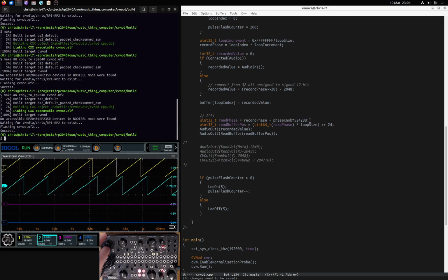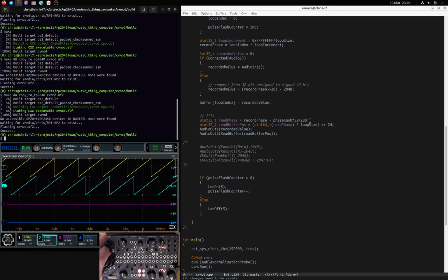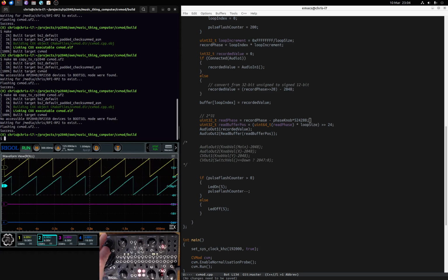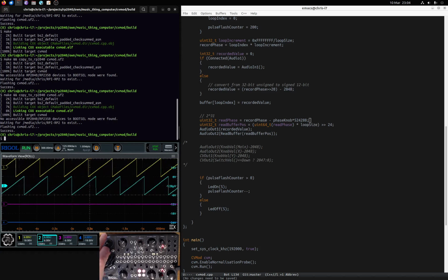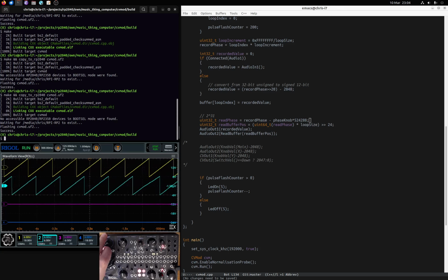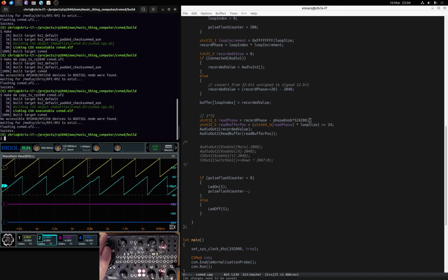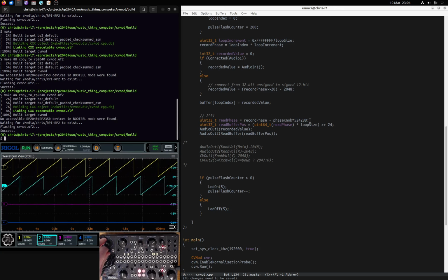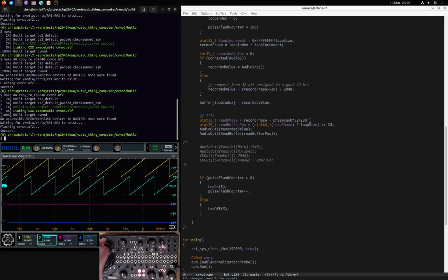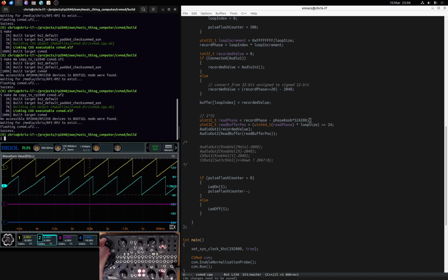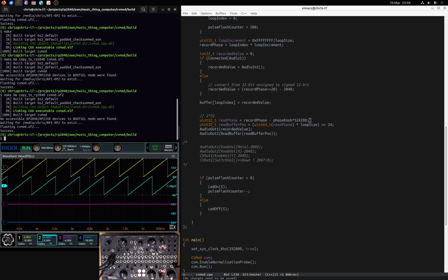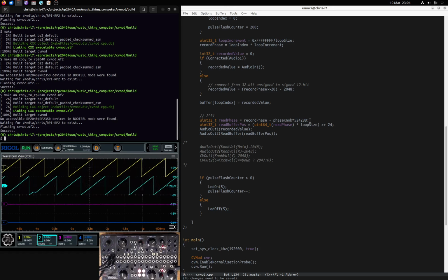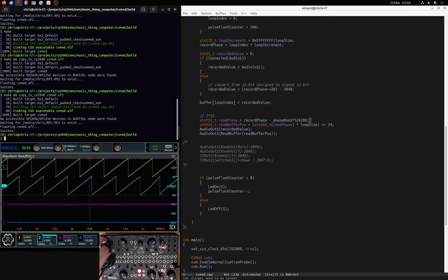yeah. So as I increase the knob Y, the blue signal is delayed from the yellow one. Initially, I thought it was in advance of the yellow one, but that's because my brain was thinking in terms of a normal oscilloscope rather than this in roll mode. And in roll mode, you can see that the blue signal being shifted to the right is the delay. If I turn that all the way, we should get 180 degrees out of phase now. Good, okay, so that is controlling the phase.